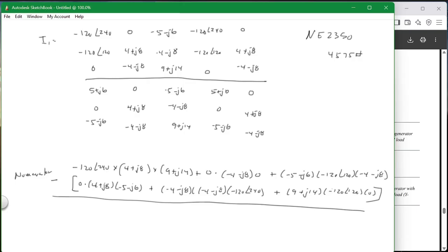The only thing about soldering that you have to remember is, there's wire in there, and please use the 22 gauge solid wire, even though, what's the difference between solid and stranded wire? Solid wire will break on you. It'll eventually break. So you shouldn't use it in an actual application. You should use stranded wire. But for us, we don't care, and you can bend it and it'll stay where you want it, and it won't fray on you. So it's a 22 solid wire, and you can use that to land on your limit switches, and you can use that for all your wiring, and it works. You don't have to go out and get another kind of wire or anything like that. 22 gauge solid wire works great for what we do.